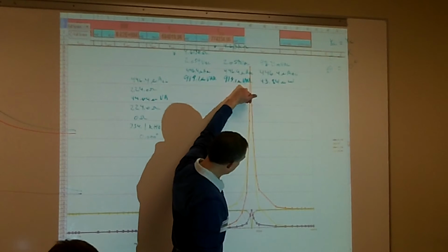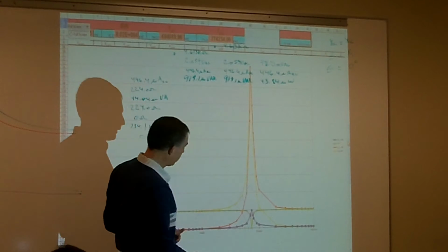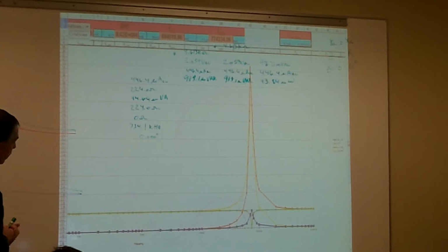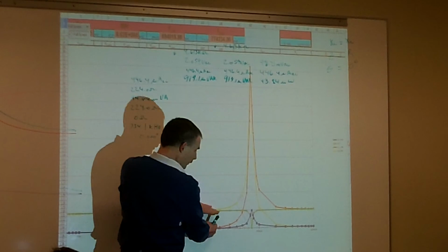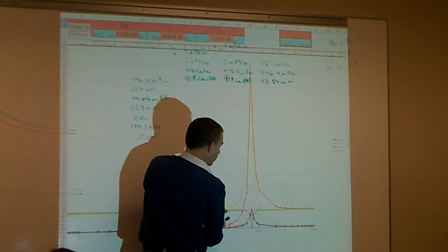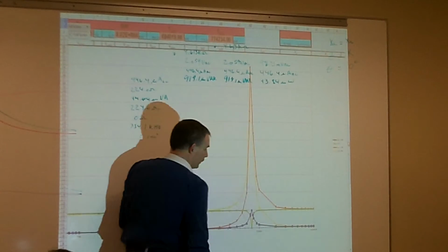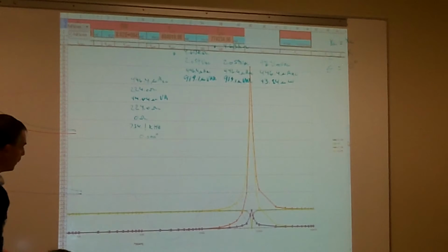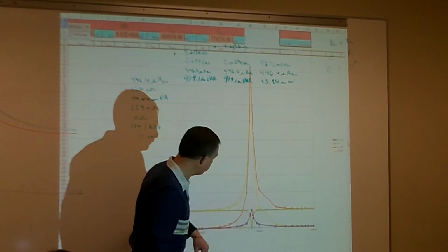But the voltage across my inductor and the voltage of my capacitor is going to be at its maximum at that point, right at my resonating frequency. And so you can see nothing really happens at my lower frequency, and then all of a sudden I get to my resonating frequency and the whole thing starts to react. Then I get past my resonating frequency, and it just stabilizes back out. But it gets very active right at my resonating frequency.